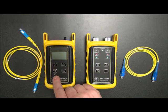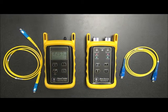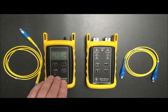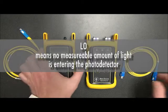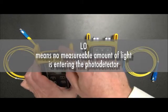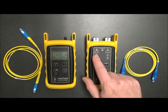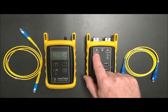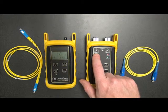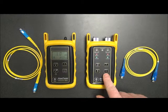So, first thing we need to do is press the power button on both testers. As you can see, the WaveTester powers up, and you'll see that the word low appears. What this means is that the dust cap is on and that there's no light coming into the detector. On the WaveSource, you'll see that the multimode port is active by default when you first power the unit on. Since we're testing single mode, we need to switch over to the single mode port. We do that by pressing the port button.